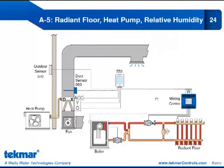Our second stage of heat will be from the heat pump. So our Y is going to the heat pump. And because we're using a heat pump, our GO relay is going to operate the reversing valve. So we have it set to O here in the diagram. Our accessory relay, in this case, will operate a dehumidifier. And we're going to be using the DX coil for dehumidification. So we talked about that earlier.